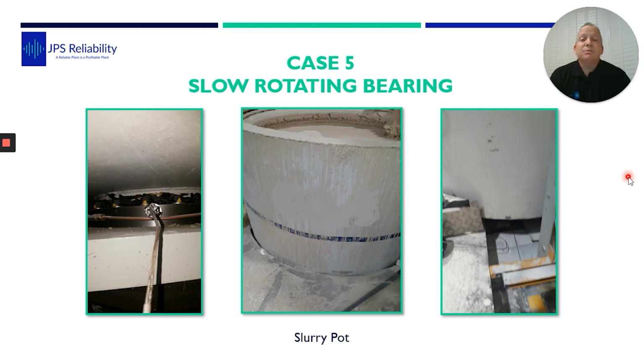The transducer we used on here was a very good quality 100 millivolt per G, and it had a high powerful curved magnet, so we got good surface contact.